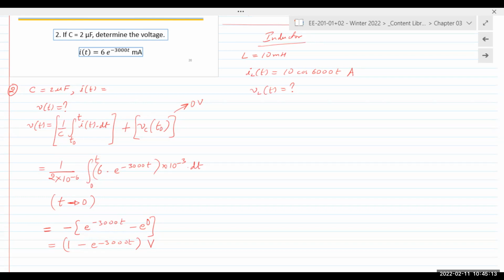So again, I is given to us. We are asked to find voltage. We determine that the equation we need to use is V is equal to 1 over C integral of the current. The current is being integrated or summed up over the time period minus infinity all the way to t. T is the end point, but it is not specifically given to us in the problem itself, so we don't really care about it. We just find our answer as a function of t.